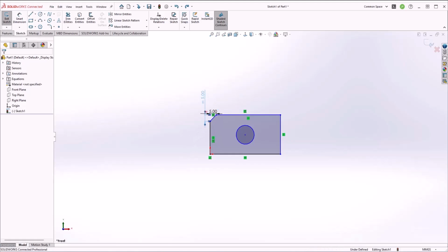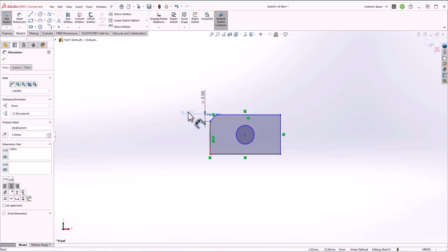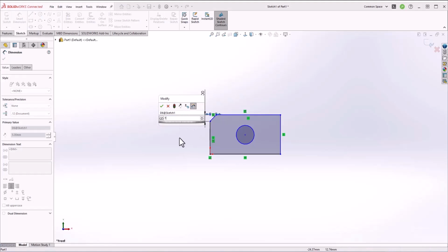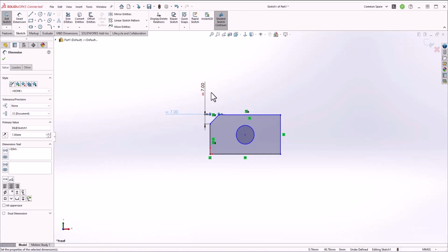Now, if you want to change the chamfer length, you can change it using any of these parameters. So maybe I'll just double click on this one and I'll make it 7. Press enter, and now the 7 unit will be for the second chamfer length as well. So that's the chamfer. Now the 7 unit distance is the distance between this edge and the original vertex.